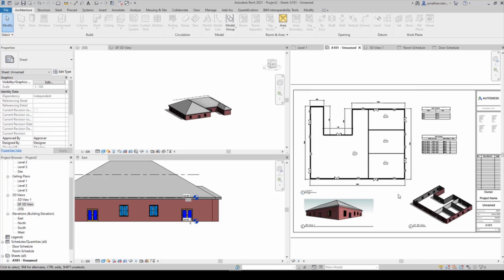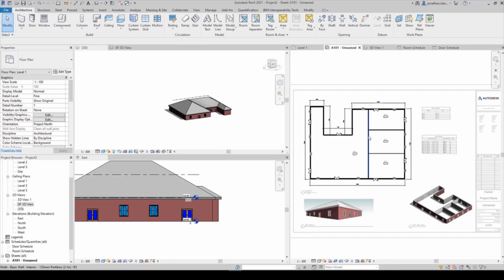And you can see how quickly you can pull something together by creating walls, creating a 2D view of that, and then using the 3D elements to place that on sheets as well. And I appreciate this design is quite basic, but you get the idea that the essence of Revit is in that efficiency by having this schedule information, the door quantification information, fire ratings, and everything pulled together and all completely interlinked as well.